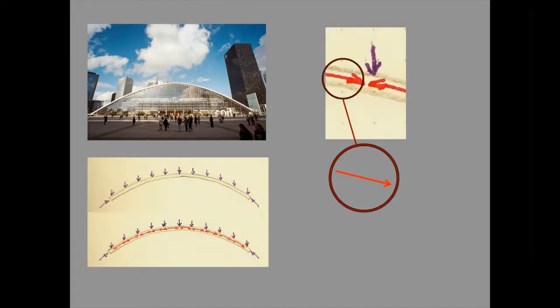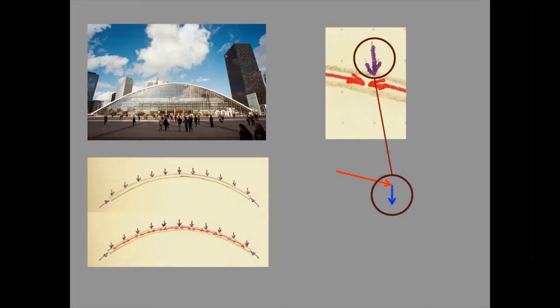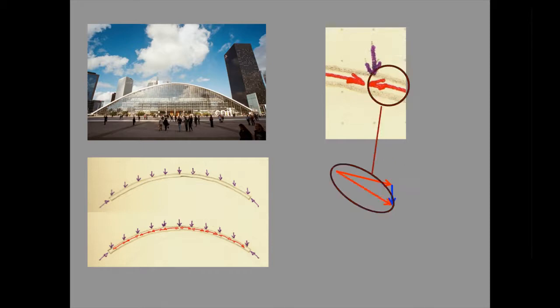This particular element is subjected firstly to the internal force from the part of the shell to its left, indicated here as a vector arrow whose length is directly proportional to the magnitude of the internal force. To this is added the vector representing the part of the load that acts on the element, and these two forces will produce a resultant. The resultant of the first two forces is transmitted to the part of the shell to the right, which supplies an equal and opposite reaction.